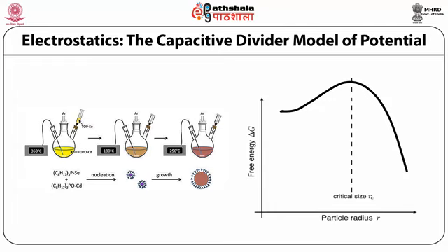However, we are interested in the opposite case, with the chemical potential of atoms in the solution being more than that of bound atoms. So the first term becomes negative, resulting in the free energy being a maximum for a certain critical radius Rc at which the nucleation barrier is imposed, as shown in this figure.